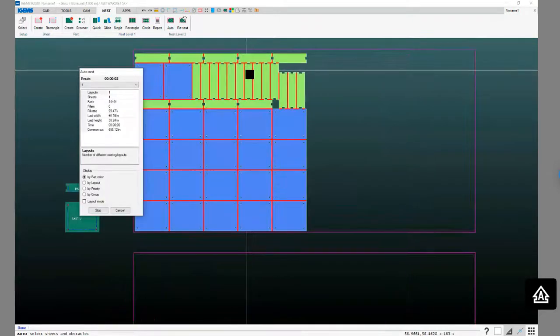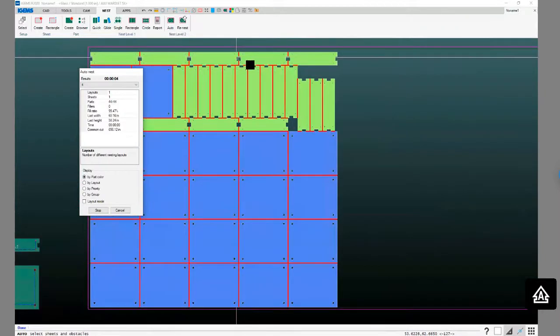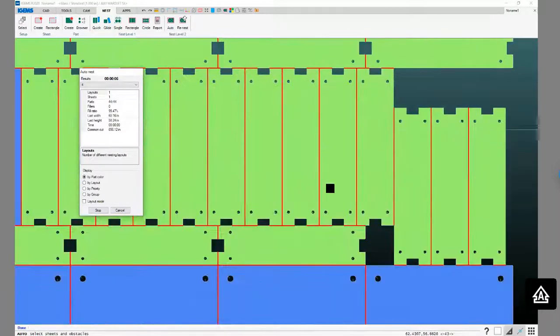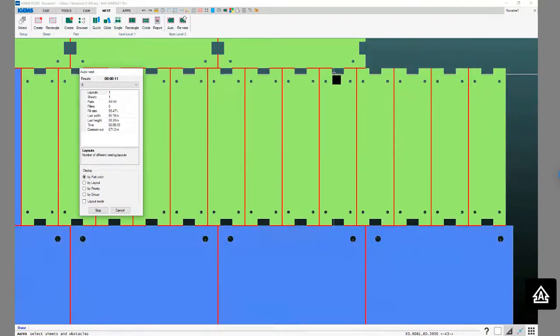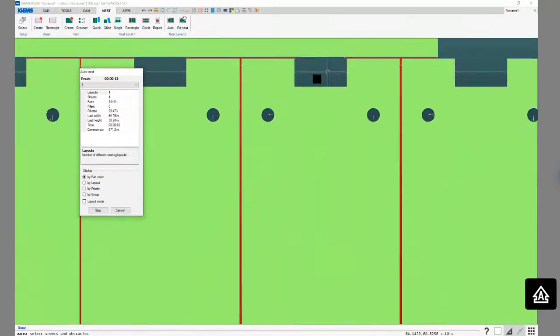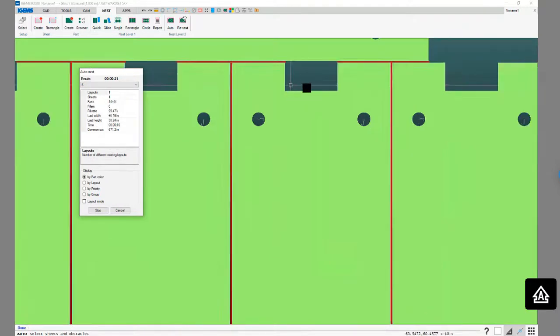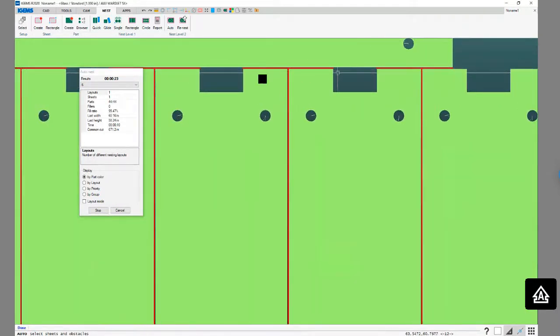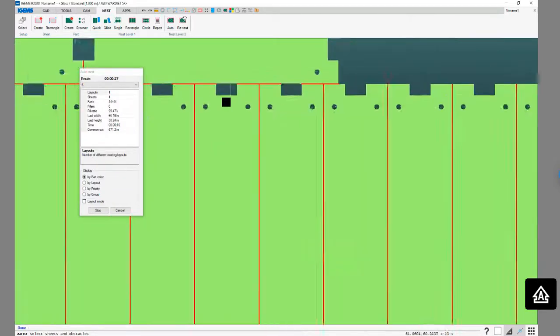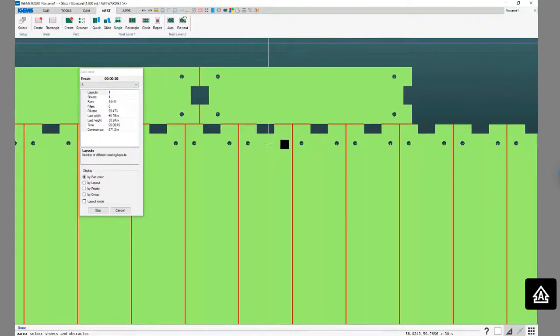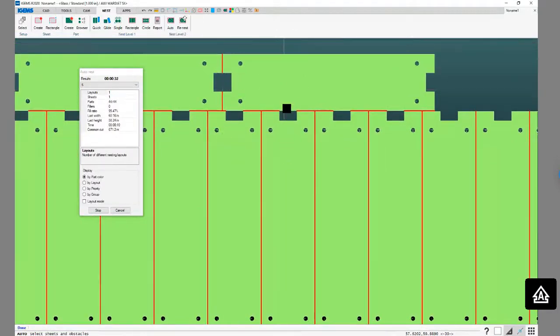So it's going to show me in red areas that it sees that might be able to do common line cutting. And I put this part in here with these notches on the end as an example of a part that might not be great for common line cutting, because when you go to add your toolpath to this, it's going to do one pierce to cut this rectangular area here, and then it's going to do another pierce to do the red common cut and do that again and again, which may probably end up taking longer than just cutting around the parts in their entirety.